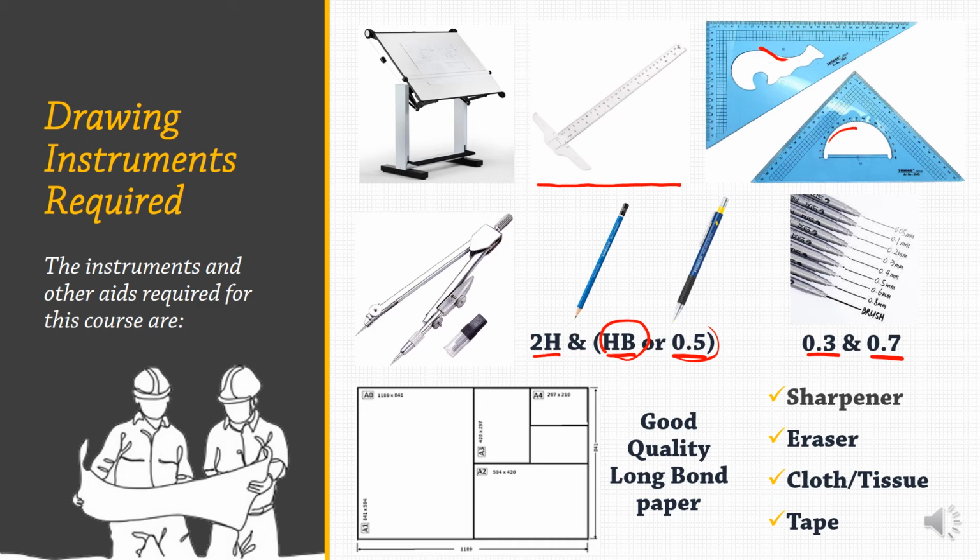But the T-square is very important in drawing because that's where all your lines start. You will also use the T-square with the set square. For example, when you draw a vertical line, you'll use your 45 degrees to inscribe vertical lines. Or when you draw an inclined line, or in isometric drawings, you need 30 degrees. You place the set square on the T-square so that, with respect to the horizontal, your lines are correct.